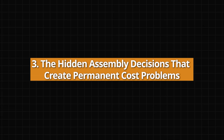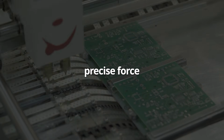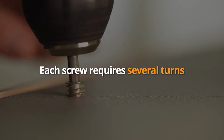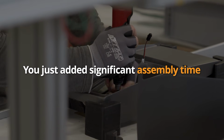Point 3. The hidden assembly decisions that create permanent costs. Some assembly choices look harmless during development, but they quietly create expensive production problems. Take snap fit connections. They work beautifully in prototypes, but in production, they often require precise force. That creates timing variations between workers. Efficiency drops. Then there are threaded fasteners. Each screw requires several turns. Add 5 screws to your product, you just added significant assembly time.